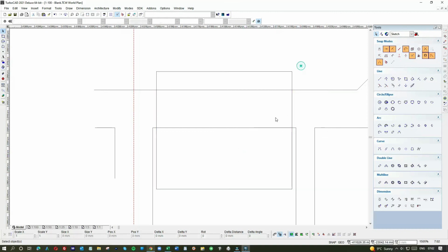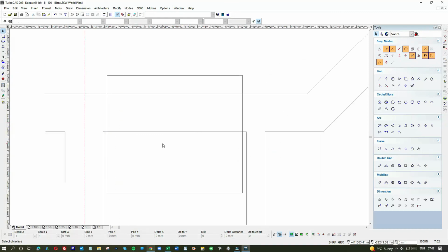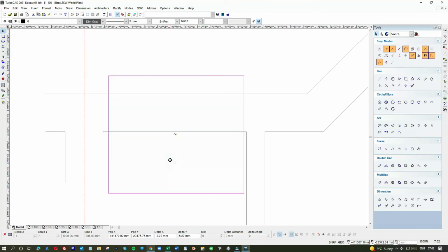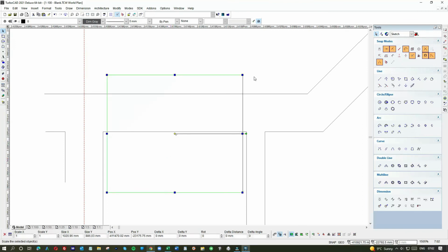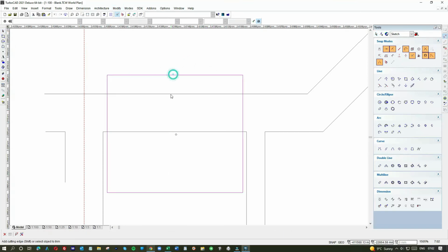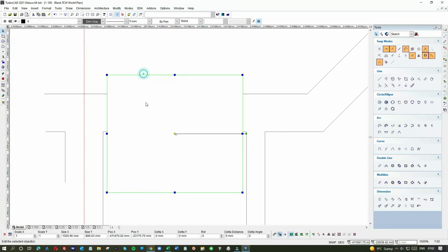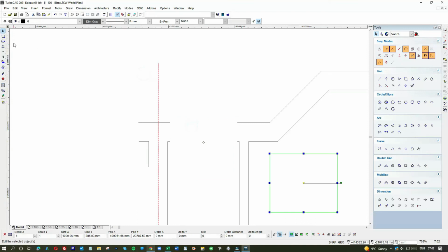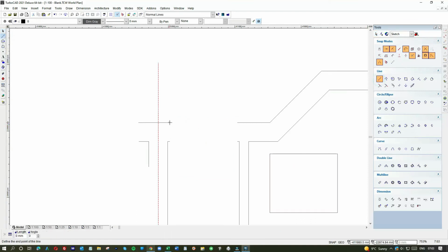Is that accurate? Nope. See what I mean about using the modify tool? If I measured out and drew a line, it would be more accurate, but this is generally representative, so it's okay. Right, modify up the top, object trim, cut and cut. Abandon the modify tool, get a few lines in. That's generally what they are.